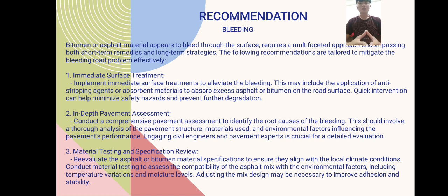The second recommendation is in-depth pavement assessment. Conduct a comprehensive pavement assessment to identify the root cause of the bleeding. This should involve a thorough analysis of pavement structure, materials used, and environmental factors influencing the pavement performance. Engaging civil engineers and pavement experts is crucial for a detailed evaluation.